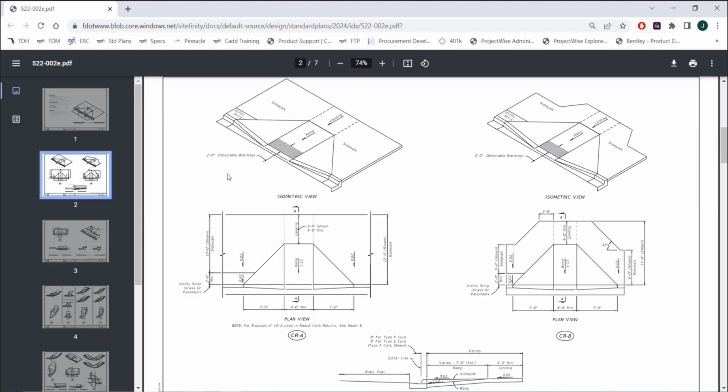One of the benefits of doing this detail modeling is that if you are tying into an existing condition, you can start looking at ADA compliancy and verifying that, all right, I have 2% here and my ramp has to be 1 to 12 or less. It could be flatter, but if it's steeper, then it no longer meets ADA compliancy. I need to revise my design and look back at what I'm doing.